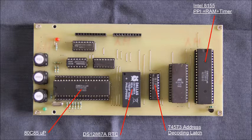This IC was specifically made to be interfaced with the Intel 8085. It has a peripheral interface with 3 ports. The third port has 6 pins and the other 2 have 8 pins. This IC primarily controls the LCD and the keypad array on our board. It also has a RAM which is 256 bytes long and is used as the primary RAM in this project. It also incorporates a timer which we are not using but is very useful when needed.